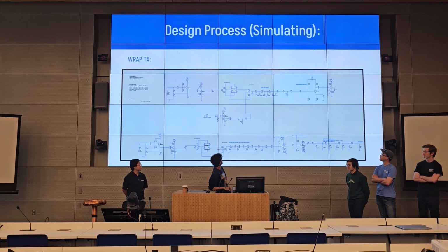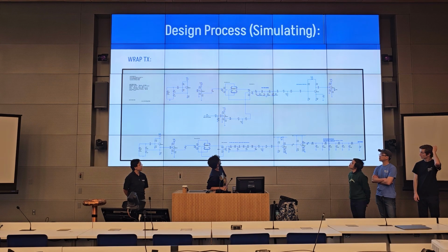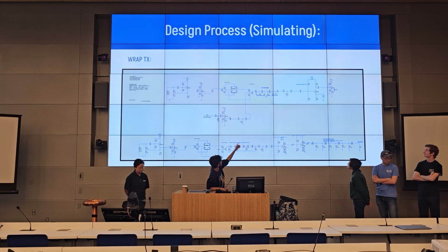Of course, we have our buffers and amplifiers to make sure that things stay isolated and perform as expected when we hook these things up together. And then, of course, amplifiers to amplify a signal. We have our mixers right there in the middle that perform up conversion. Then we have the filter, 5 megahertz over there. Another amplifier stage, a buffer, loops all the way back down over here. And then that same process repeats up to 27 megahertz. And then boom, it's our antenna.